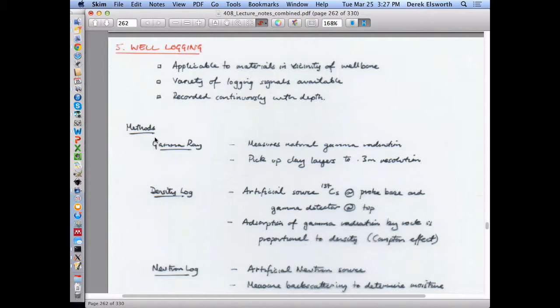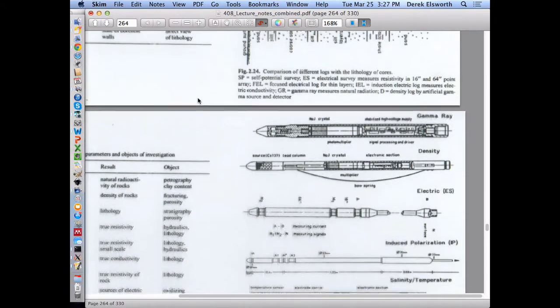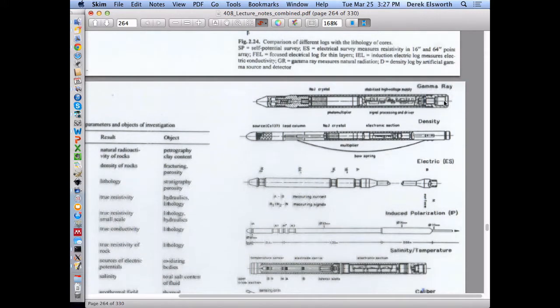And the idea is to figure out by some proxy what there is in the subsurface. So you have a sonde. A sonde is just an instrument, a tool that's physically hung on a wire line, and it's dropped down the hole at constant velocity. It has to be an uncased hole, so there's no casing that it has to look through. It doesn't go down discretely, but it just is dropped to the bottom of the hole, maybe a meter a second. It's dragged up through the hole, maybe at a similar rate, and it records some signal as it goes down and gives you a constant profile recorded as you go down, both ways.